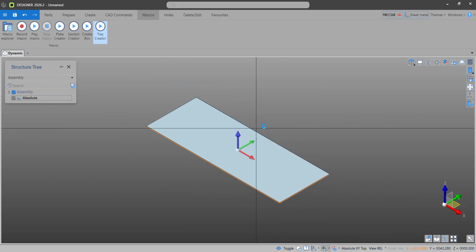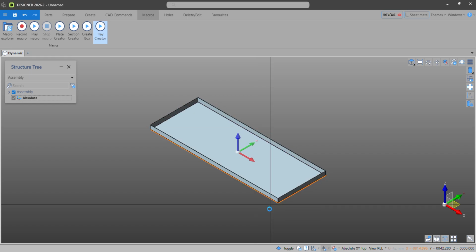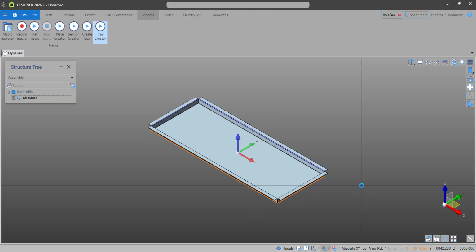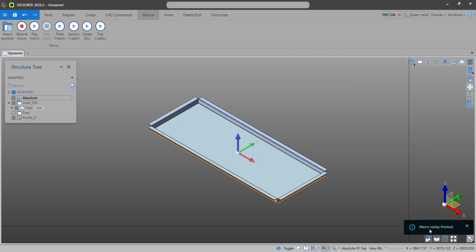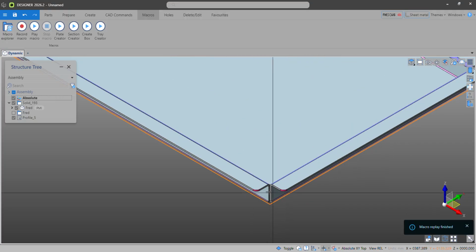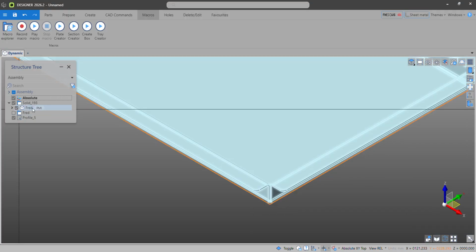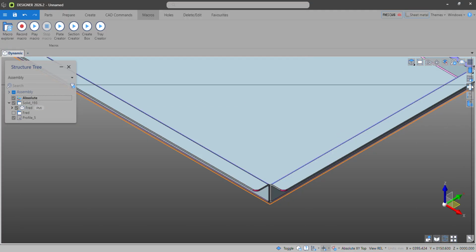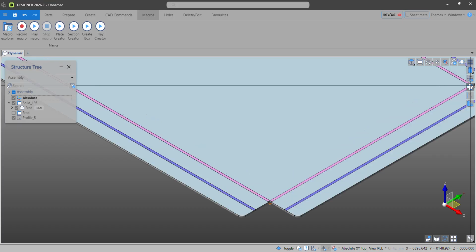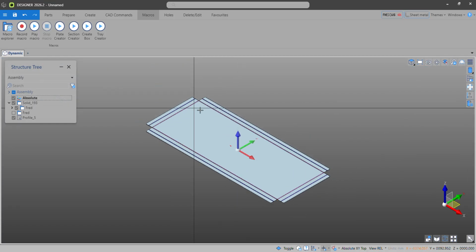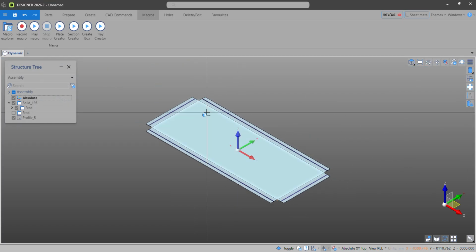You'll see the size of the tray has changed, the heights will change, and you'll see it's now doing my corners. It's doing all 4 corners. It'll add my flanges on, my returns on in a minute. Alright, and then you'll see it's actually finished, and it's put my radiuses on there as well. You'll notice over here it's also renamed it as Fred, and then of course, all being well, I'll be able to flatten that model out, and from there I'd be able to send that to my package such as Radan to get that punched or cut.